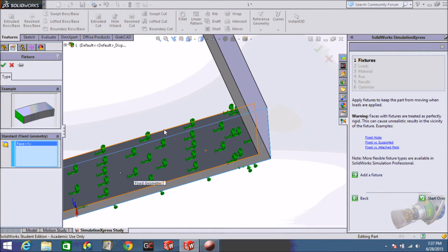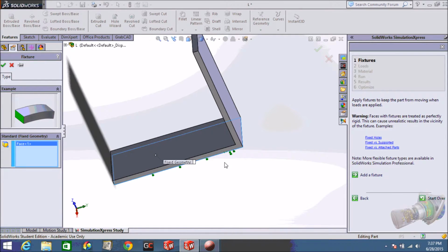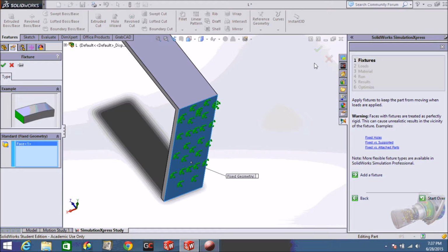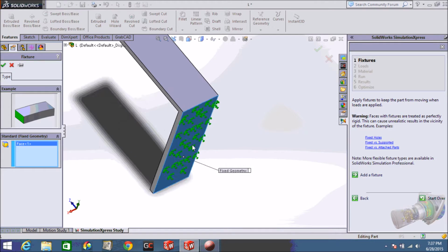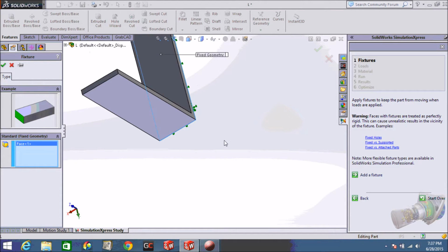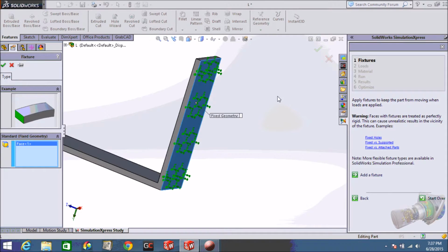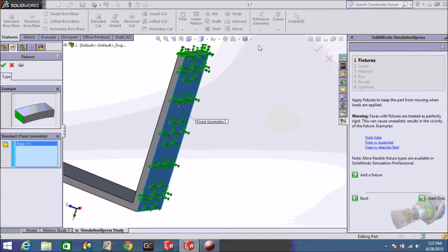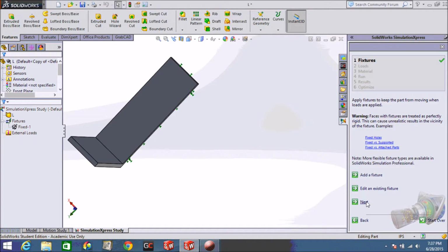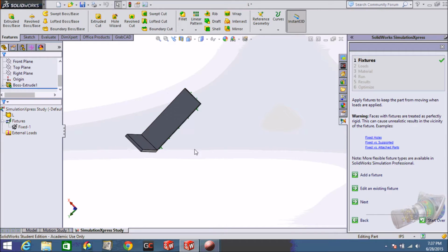There are no holes here. You cannot run finite element analysis on assemblies. So each individual part, you basically just fix the point or plane where it's attached to another part. So the best representation of this in reality would be like some super strong Velcro holding this to another piece, right? Because it's being fixed along this plane. So pretty much impossible to pull off in real life, but it's good enough for our demonstration. Once again, however you are mounting it, you want to fix the part that you're mounting.